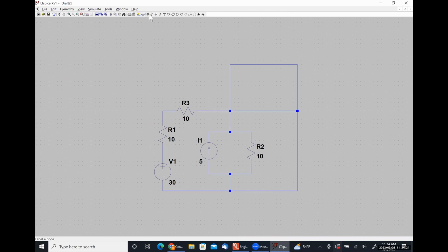And now I'm going to throw resistors in. So I'm going to do that 20 ohm resistor kind of in the right middle side here. So if I put a resistor on top of this short circuit, it's going to break the short and place the resistor there. Okay. So that I can kind of map out how things are going to go and then put the resistor in to fix things. Right. I'm going to press Control R and put this resistor on the right hand side. And then I'm going to rotate this guy again and put one up here on the top.